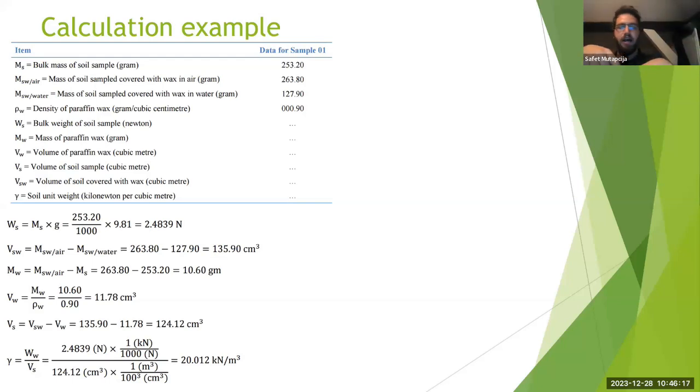You're going to put soil inside, because that's the way you're going to prepare the sample for the odometer test or for the shear test. You're going to weigh it again, and just divide everything, and you're going to get your unit weight. That works for the clay and silt, and you're probably going to work mostly with it. So it's a super simple test.